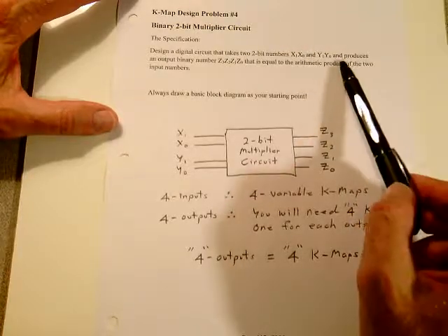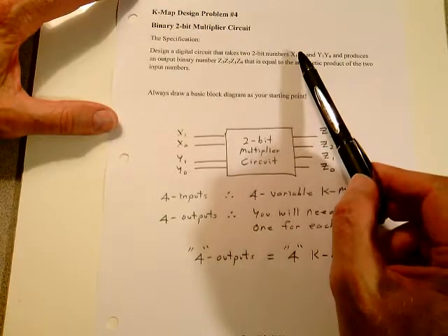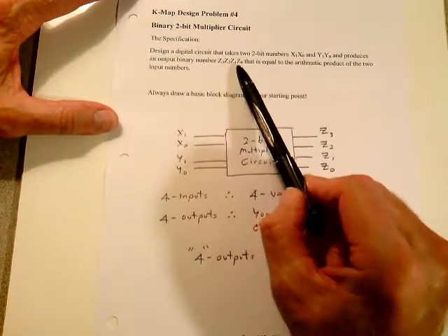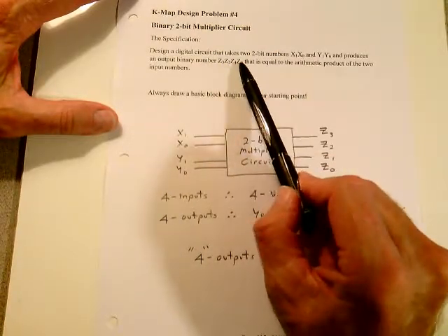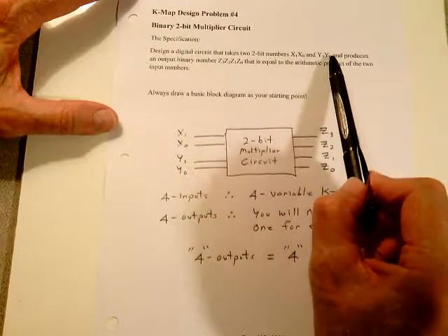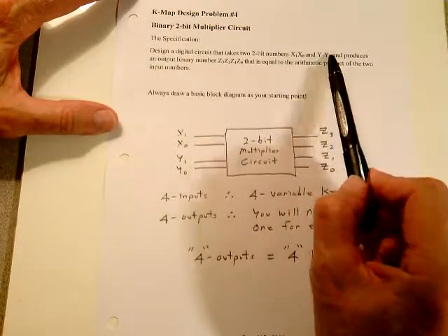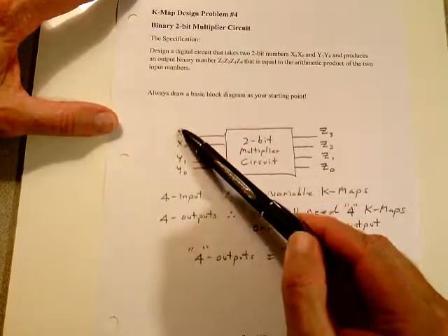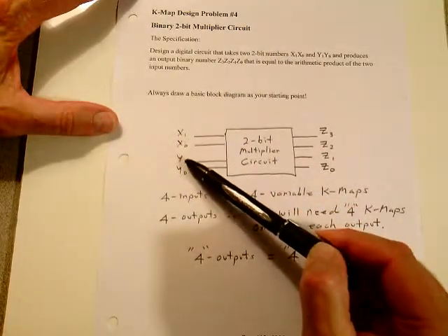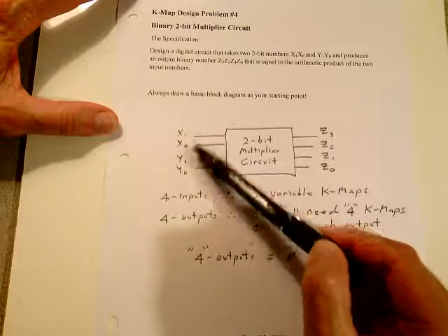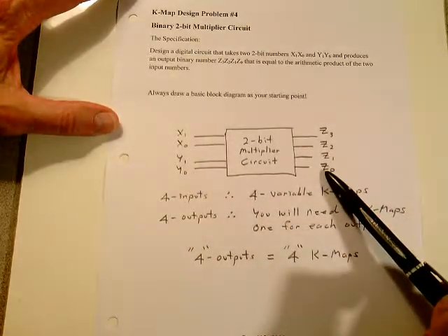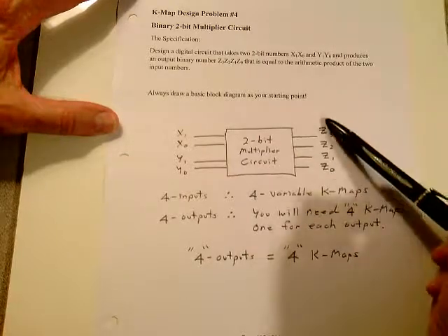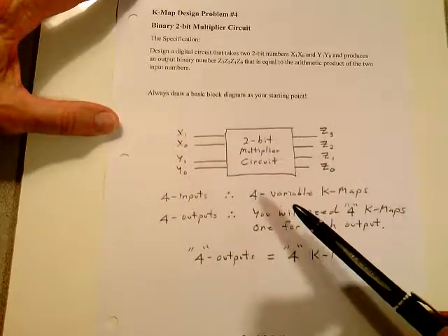So let's take an example. 2 times 2 is going to give you a 4. So you only need 3 bits to show 4, 1, 0, 0. But what if this was a 3 and this was a 3? A 1, 1, and a 1, 1. A 3 times a 3, the output's going to have to be 9. If this is a 1, and this is a 1, and this is a 1, and this is a 1, that's a 3 times a 3, so you should get a 9 out here. 1, 0, 0, 1. That's why I'm showing 4 output bits.